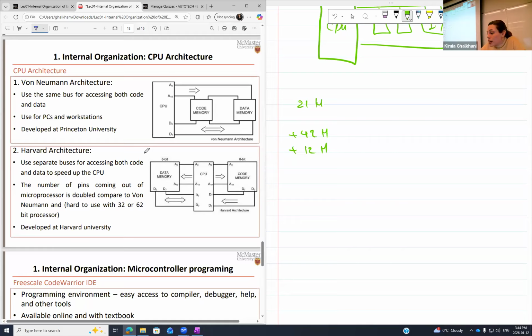In the von Neumann architecture, you will have access from the CPU to the memory on the same bus. And now you know what a bus is. Memory, and again, in here, you can see it's the same bus. All of the accesses are through the same bus. When you are doing read and write, you are using the exact same bus to read and write into the CPU. So the results of processing need to be written to the memory. Then you have a control box or control bus in here.